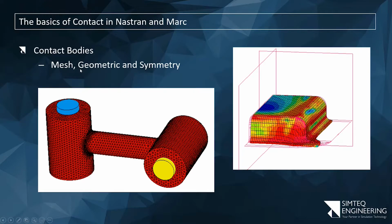Okay, now in terms of what can make contact, we always make contact at nodes, because that's how we transfer information to a mesh. So that means a mesh can touch other meshes. In other words, this node can touch a face somewhere over there, for argument's sake. But we can also touch geometric surfaces, or symmetry.